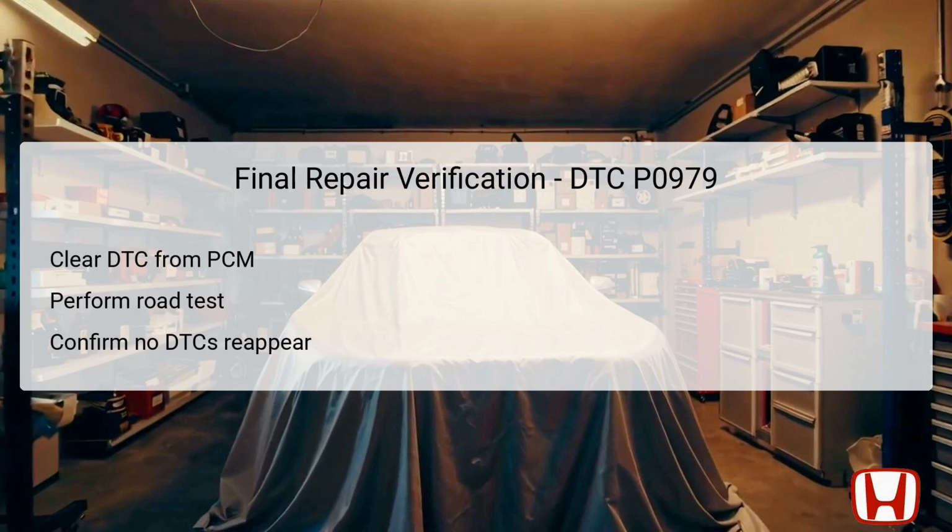During this test, pay attention to the shifting behavior and observe if the AT gear position indicator operates normally without blinking. After the road test, recheck the DTCs in the PCM to verify that the DTC P0979 does not reappear. This thorough approach ensures that the repair has effectively addressed the underlying issue.